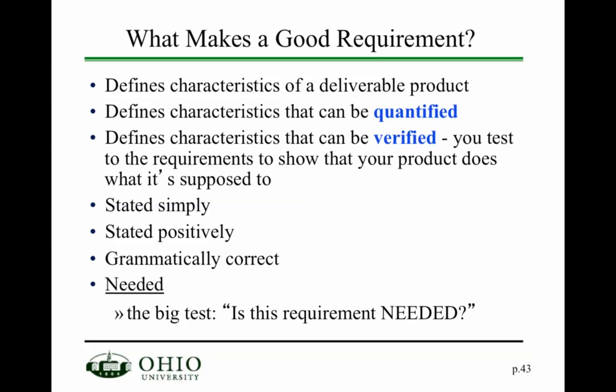If I make a requirement for a system that tests if the volume of fuel in your tank falls below a certain level and then, for example, provides the driver with some kind of warning, like an LED, then you must be able to take that requirement and test it. And you can do this, for example, by lowering the volume in your tank and checking if the LED or whatever warning you have still comes on.